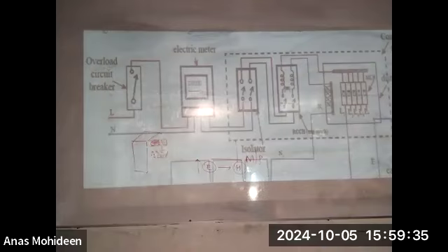Moreover, if you have a problem within the kitchen and you are going to renovate, the correct method is to turn off the main switch. Yet you can turn off that MCB's area and then do your work. But the exact right method is to turn off the main switch. Okay. Is that clear? But what our electricians do is not the practice. Whenever there is an issue, straight away they take the bulb out. It's very dangerous. Why? Without turning off the switch, remember, if your hand touches a 230 volt supply, you will be left hanging.